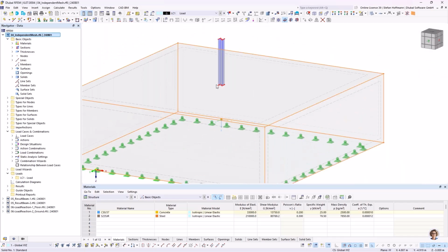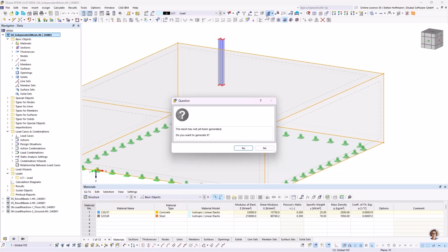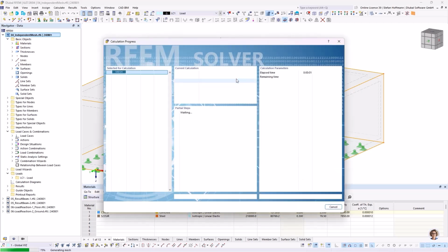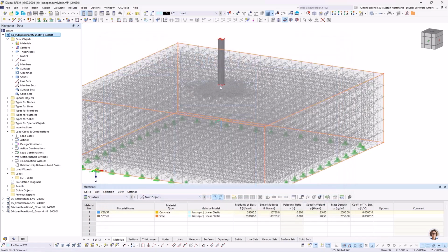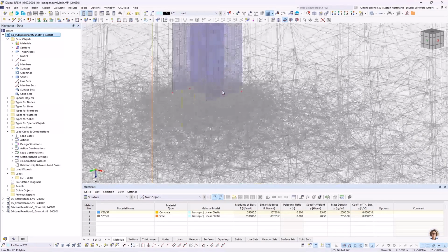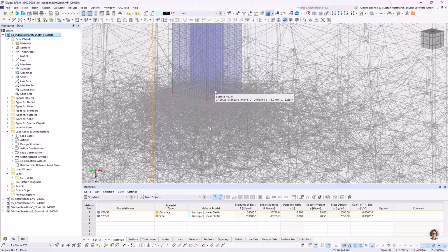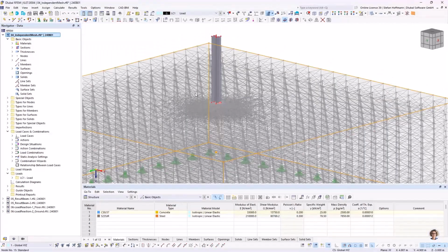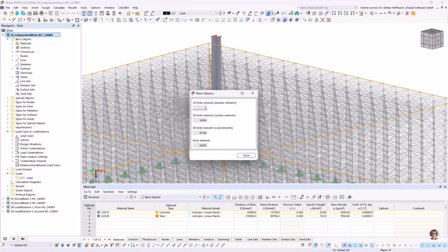And if you then have a fine mesh in here connecting to the solid body, it needs to be connected at FE mesh nodes. If we, for example, generate the mesh without any extra setting done to it, then the mesh will most likely have such a fine representation, because the fine mesh of the surfaces needs to be directly connected to the solid in the ground. This will lead to a high statistic of 3D elements, 47,000.